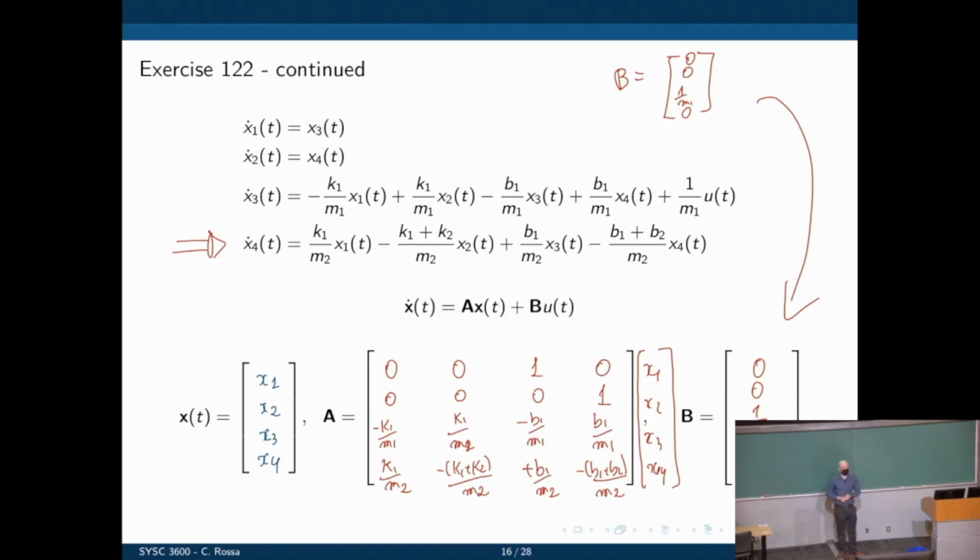And now you can clearly see what influences what in the system. We can see the parameters that will influence the rate of change in the states. That's the big matrix A. And you also see where exactly the input affects the states. That's matrix B. And then through B, A is affected, and the system evolves that way.